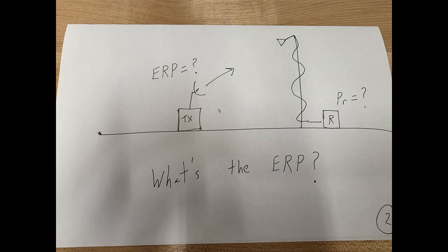Well, one approach is to simply set it up there, and somewhere in the far field you have a horn with a coax cable hopefully attached to it, and you hook that up to a spectrum analyzer, measure the received power, and compute the ERP. Now, to do it this way, you're going to have to know the distance to the horn, what the horn gain is, and measure the coax loss, and so on. So this is kind of a stupid way to measure ERP, so Dr. Moonshine's going to give you the better approach.